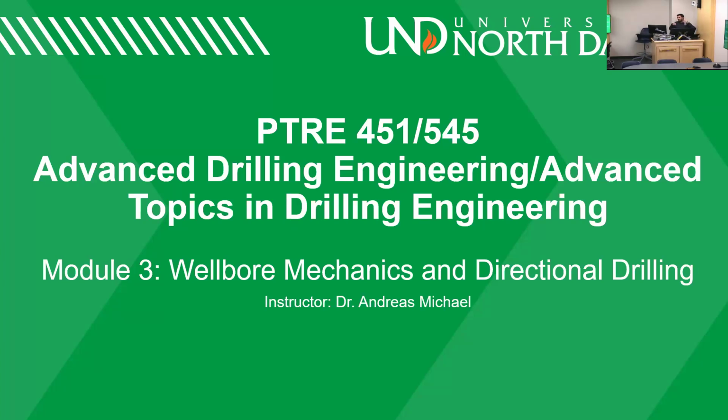But if you keep it constant, if you have it on auto, when you are drilling and you get a kick, it is pushing the drill string up. So the reading that you have of the weight on the bit decreases, it goes down. Some people didn't put it in the exam, and I was going to make the TA take 1 point off, and then I realized that it's not going to help anybody.